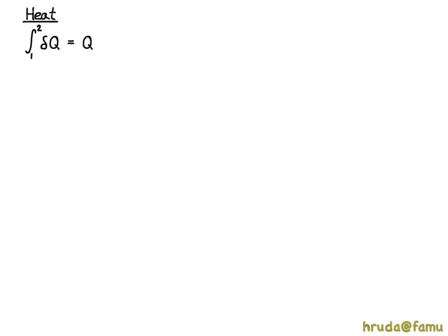But getting back to heat, we can say the heat in going from state 1 to state 2 is just the integral of del Q. In some textbooks, they don't put the 1 and 2 on opposite sides. They'll put it on the same side. That's not Q12. That's the heat transfer in going from state 1 to state 2.